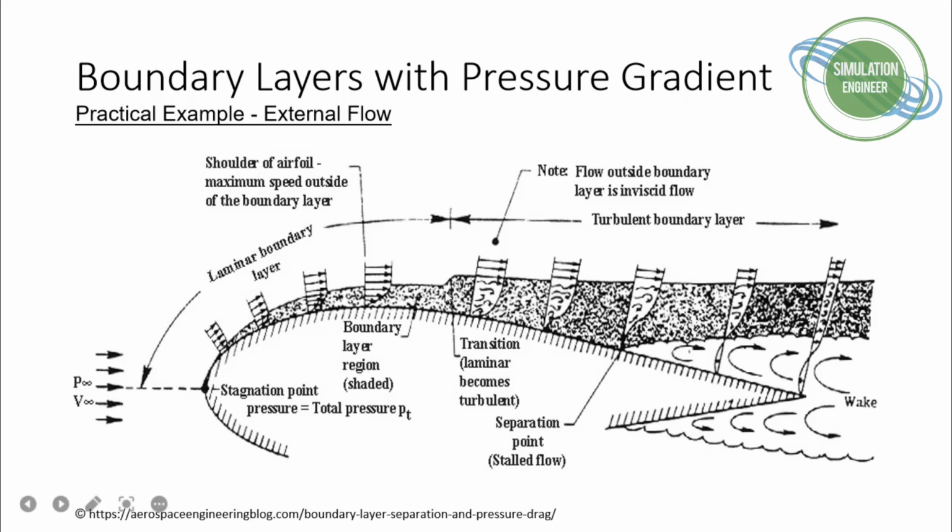So now, this is the transition region. We have examined that it is almost here, this point, and before this point is the laminar boundary layer, and then the flow starts to become turbulent. This can really be seen with this fuller shape of the boundary layer, the much stronger gradient compared to the laminar flow. And then at some point there will again be an adverse pressure gradient. You will see here, this is the point of inflection, and you go further downwards, you have wall shear as zero at this point. The flow is now at this separation point, and then if we go further downstream, we have a very strong excessive adverse pressure gradient, and the flow is fully separated near the wall. We see this flow reversal, and we can see this nice symmetrical wake, which is producing a trailing edge flow separation on this airfoil.